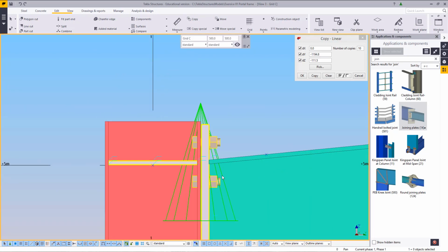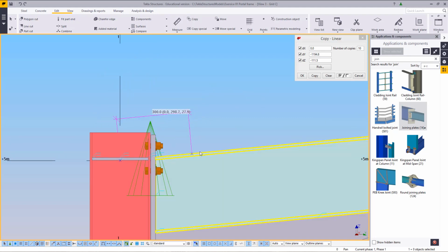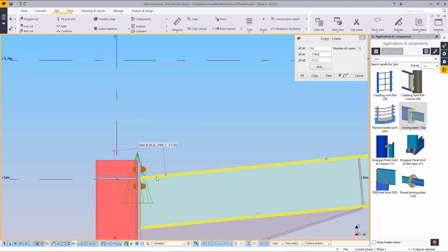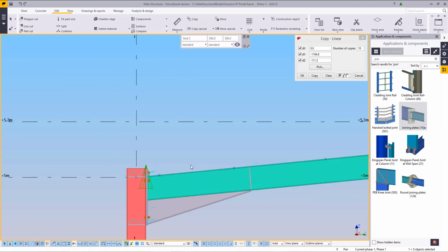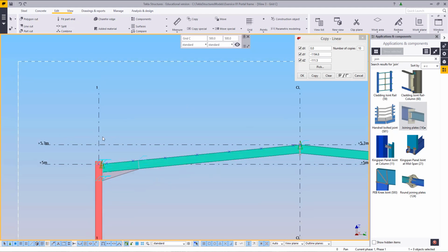Again, a good way to quickly do things. Do note that when you're doing this, be very careful that you are snapping on the line and not to another point in the vicinity, as it could cause problems. Now, once all of this has been done, I'm going to change my selection to only feature these points.